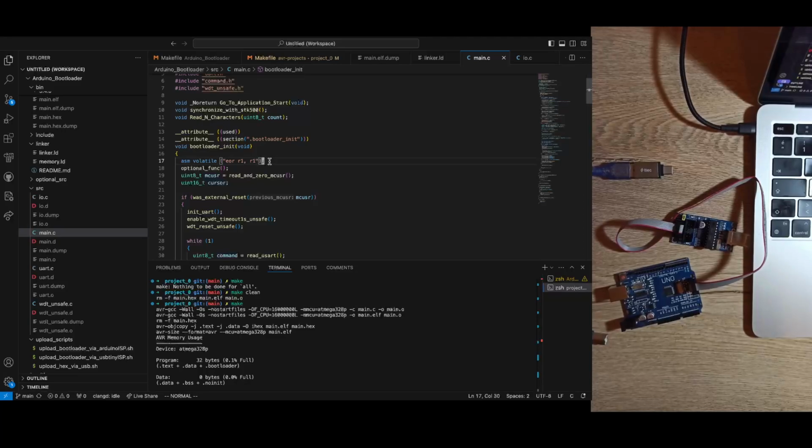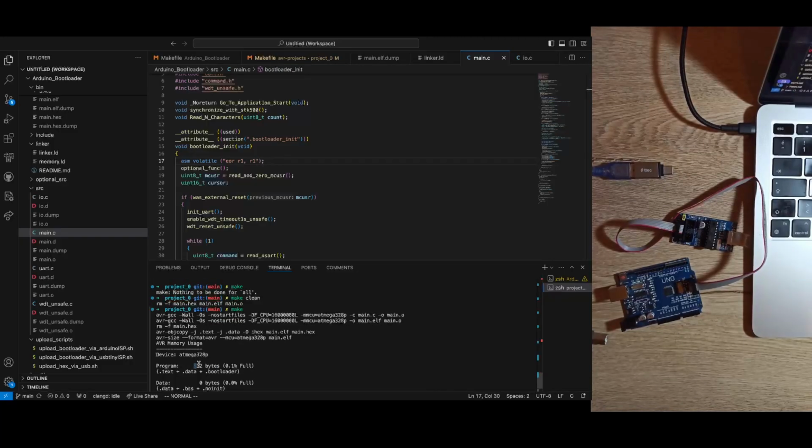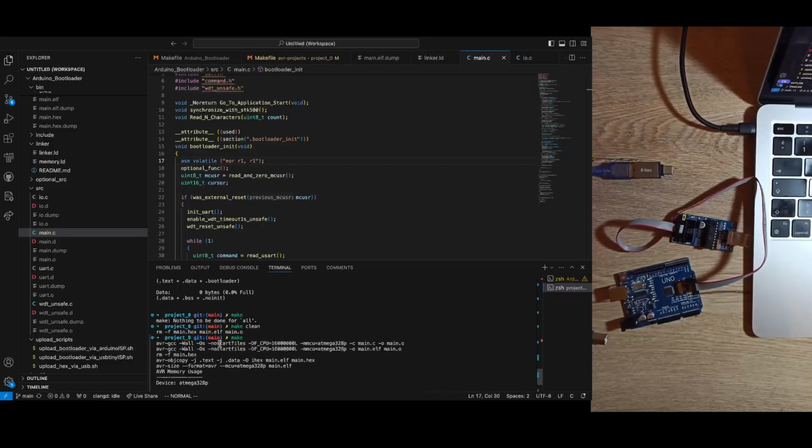Also, C programming assumes a stack management system is in place, so the stack pointer is initialized properly at a proper value. It's not going to automatically do that for you. So the start files actually do that. And if we remove them, we actually gain space, but we lose functionality.